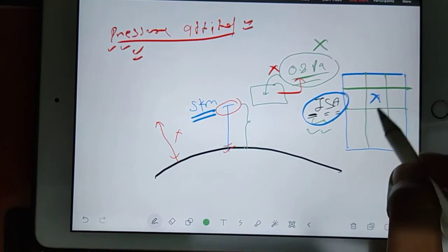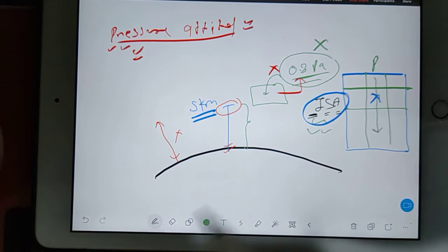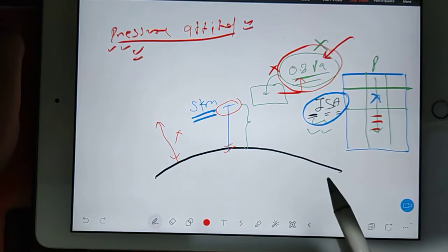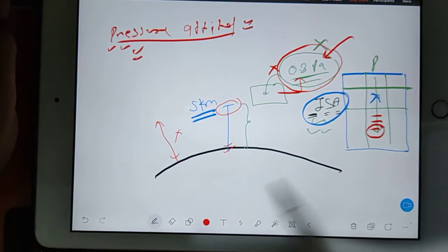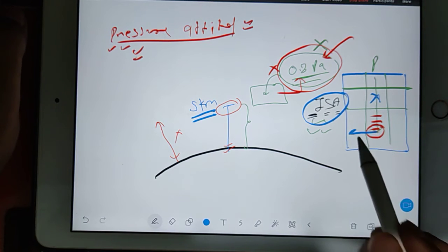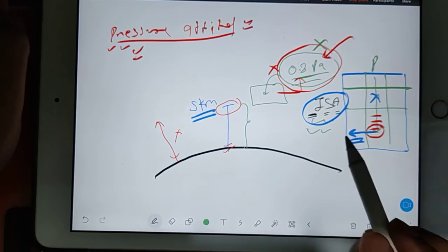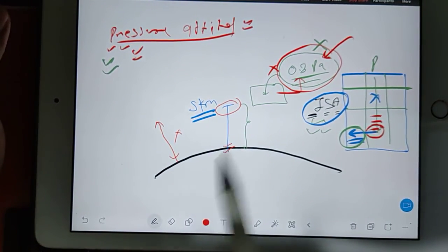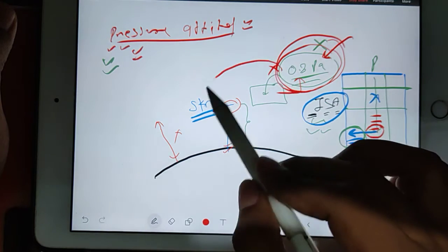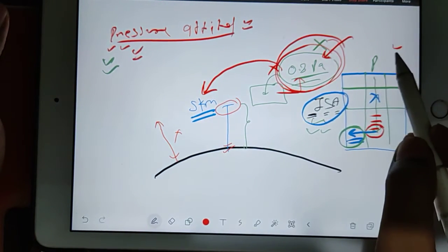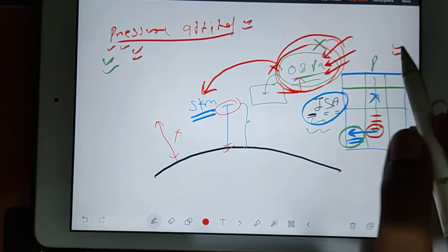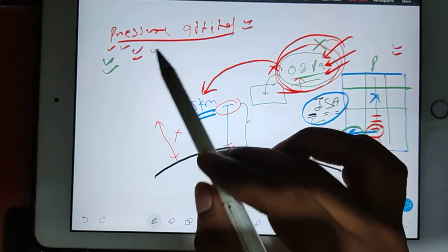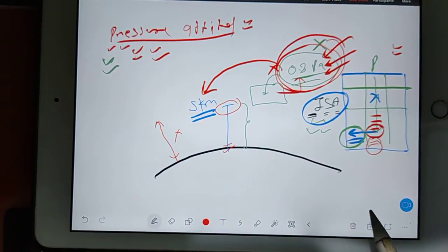Okay, so you go to the pressure table and you check where 0.8 Pascal is written. Wherever 0.8 Pascal is written, in front of that, what height is written? That height will be your pressure altitude. It means in real life 0.8 Pascal we are getting at 5 km, but in the ISA table the same pressure we will get at a certain other altitude. So that new altitude will be your pressure altitude. I will repeat again with the help of temperature altitude.